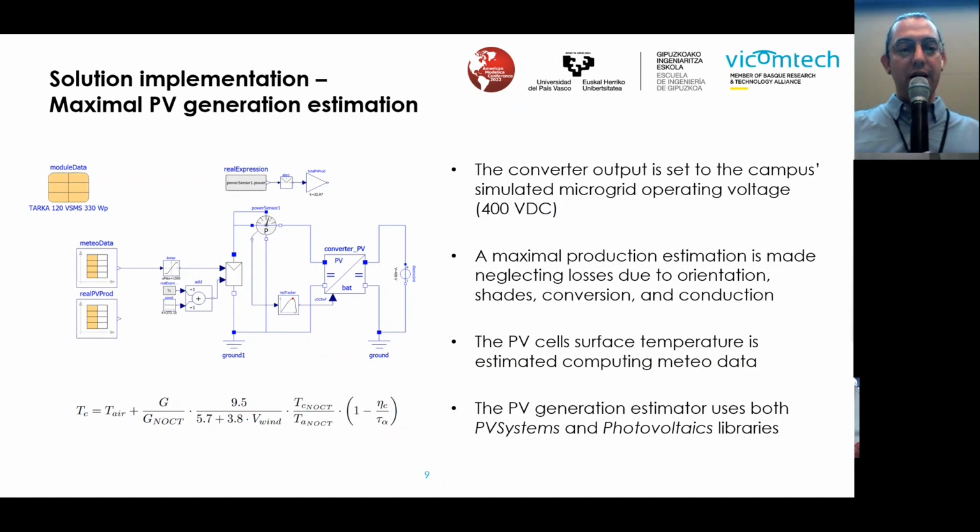They're using, including DC to DC converter, which is a little bit strange, but the idea here is to calculate the total kilowatt power production. So you can model this as a DC equivalent and calculate from that the total demand. So you don't care what the kilovolt amperes are, only the kilowatts. Okay. So the DC to DC converter that you see on the screen is basically an average model because they really are not that interested in any of the other characteristics like the voltage, for example.